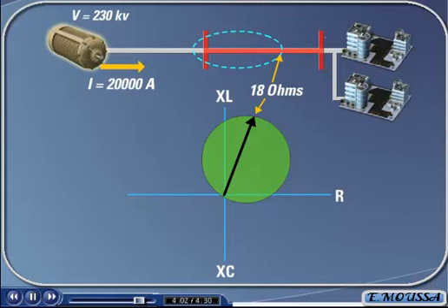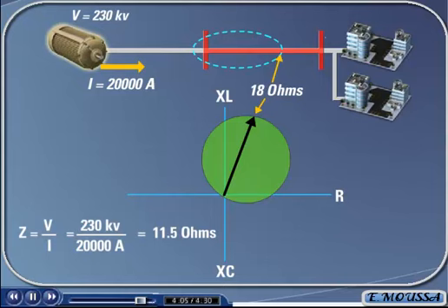Even though there is no fault on the transmission line, the newly calculated impedance of the line would be less than the reach of the Mho circle zone. However, since the load that was added is mostly resistive, the plotted impedance point would be much closer to the origin of the graph, but still very close to the x-axis. Since the Mho circle is positioned where it is on the graph, there is very little area included in the zone of protection in the resistance direction. Therefore, the new impedance will not fall into its zone of protection, and the relay will not trip.